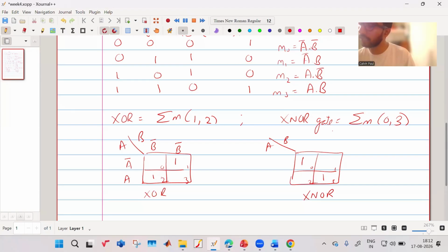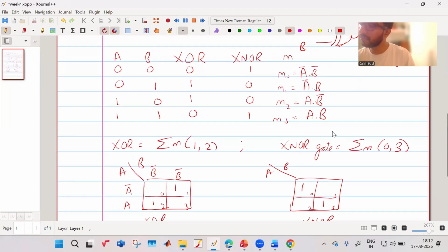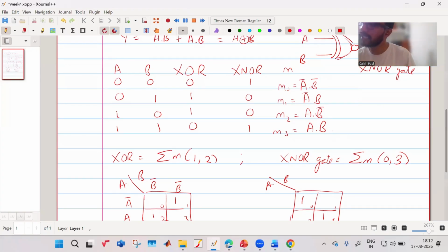So your XOR gate will give you a 1 when there is only a single 1 in your circuit input which is high. When does the XOR gate give output 1? When an odd number of inputs is 1. That's why XOR is known as an odd function.